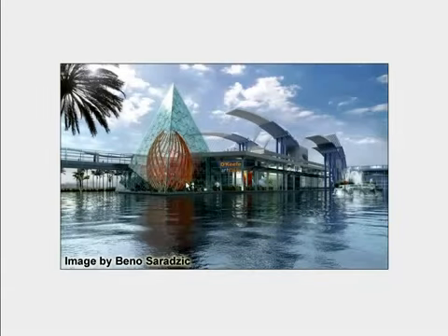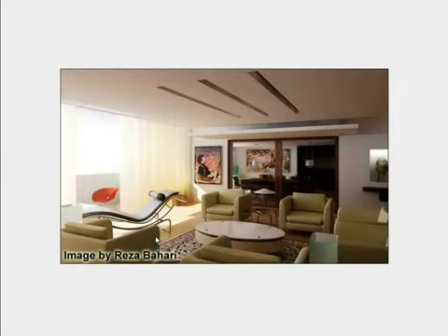In this particular image, I would use adaptive QMC because while there is detail that's needed throughout the scene, it's really confined to just a few areas. The palm fronds in the trees and these lines here in the building. There's a large amount of area in this particular image where detail is not needed, such as the sky and the water. So you could definitely save some rendering time by using the adaptive QMC sampler here. And again, you might just need to experiment to figure out what settings you need to set the min and max values at.